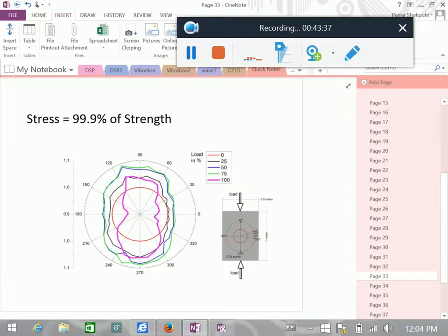People know that. But it took me 1.5 years, so people didn't even believe. Like, you had to really show them. So we did acoustic emission next to it. You can see when you are starting to have a lot of events in acoustic emission, that's when the velocity starts to drop. I didn't include that here, but it is in our papers. So we basically proved to the community that really this is also happening in concrete, and it is significant. You can't just ignore it.